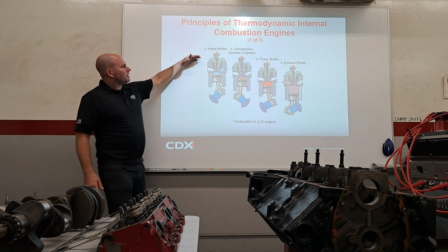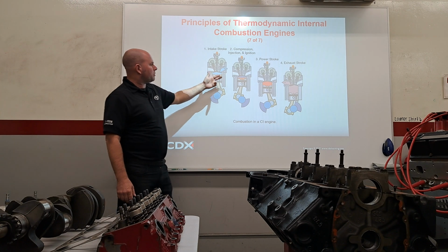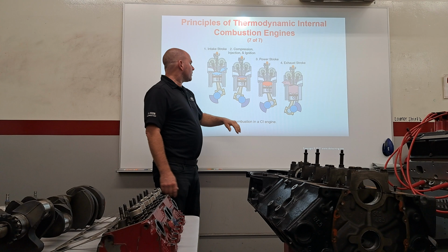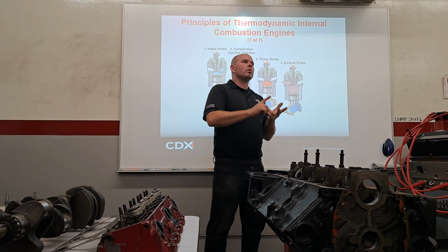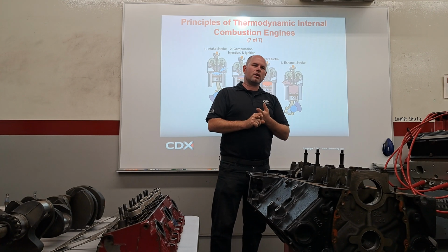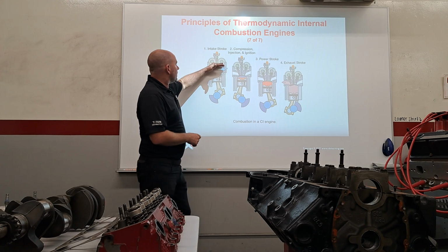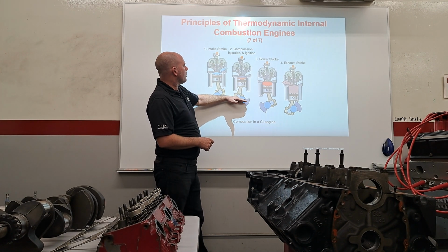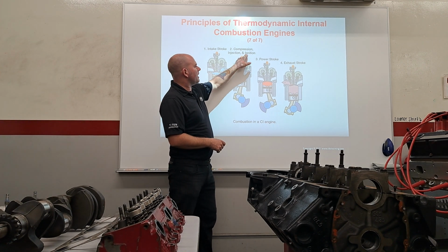Now this one is a little bit different because I don't see a spark plug here. There is no spark plug. This is a diesel. Diesels are still 4-stroke, by the way. You may call it 4-stroke or 4-cycle. So if you hear 4-cycle, it's 4-stroke. Cycle, strokes, same. Intake, then look right here. This is compression, but it also says what? Injection and ignition. That's kind of weird.